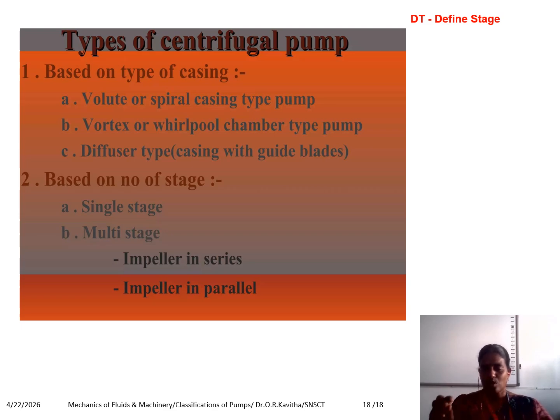The multi-stage may be used to raise the water to a higher level, that is, to increase the head of the water, that is one thing. Another thing is to increase the discharge of water from the pumps. So the centrifugal pumps are used either to discharge more water, or to increase the head of the water. The multi-stage will be classified like this.